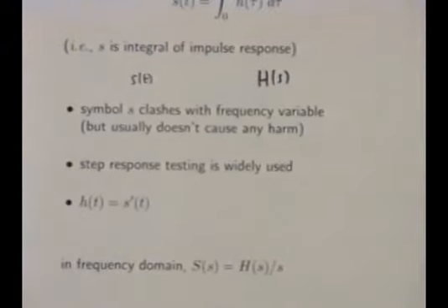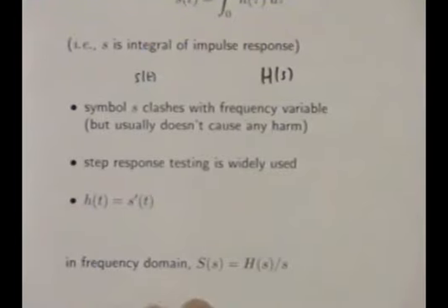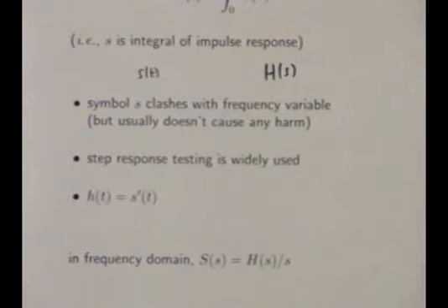Okay, and that's very widely used. Many fields will show you the step response of a system. That's very common. For example, if someone shows you a power amplifier or something like that, they will show you a step response. For electromechanical systems, very common to show the step response. But even for all sorts of other strange things, like, for example, an industrial furnace, where you want to control the temperature, a step response will show you the change in temperature when you change the power input to the heater. Many other areas you'll see a step response.